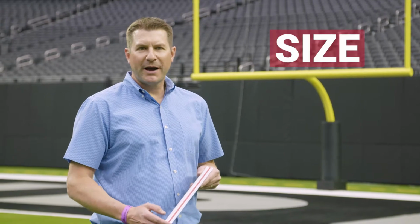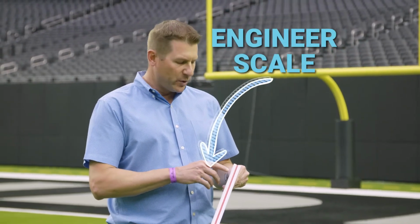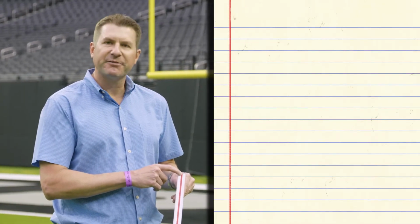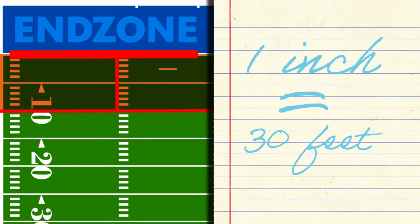So when we talk about size and scale and proportion, I've got what looks like a ruler here. This ruler is actually an engineer's scale, where we use a measurement of 1 inch to equal various quantities. Like in this perspective, 1 inch equals 30 feet. That's the same distance from the 10-yard line to the end zone. That's how we're able to fit a building of this size on architectural plans and drawings.